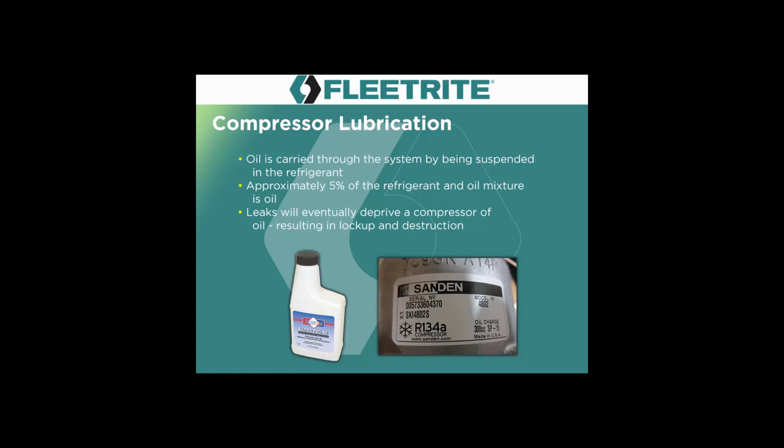The oil is carried throughout the system. It's suspended within the refrigerant charge. About 5% of the refrigerant charge going around is oil. So operating the compressor with a refrigerant leak will eventually deprive the compressor of oil, resulting in lockup and destruction, causing all the problems that we deal with on a day-to-day basis with compressors.